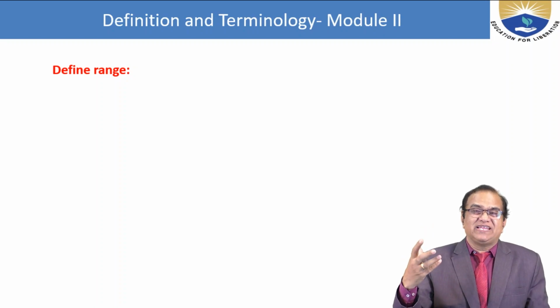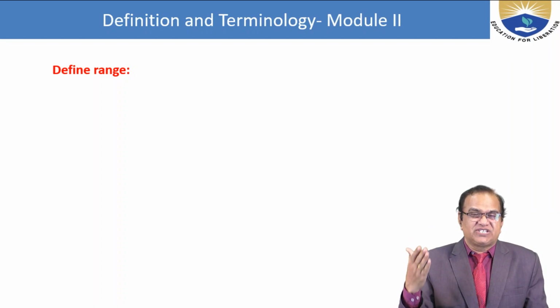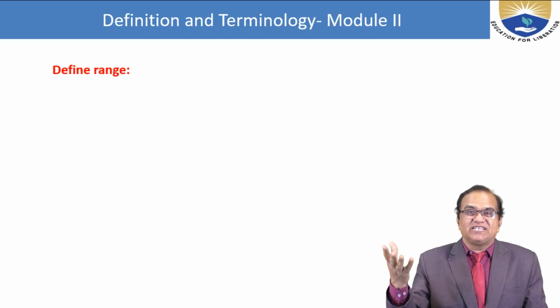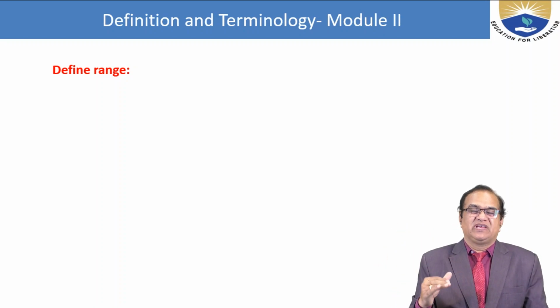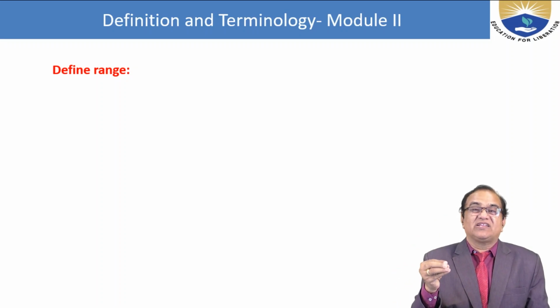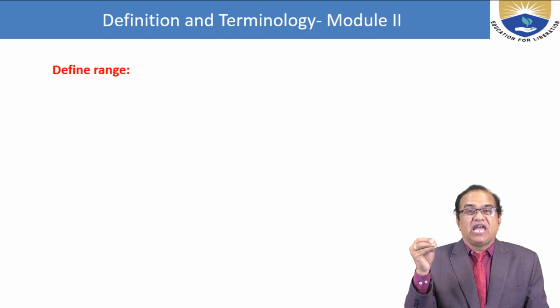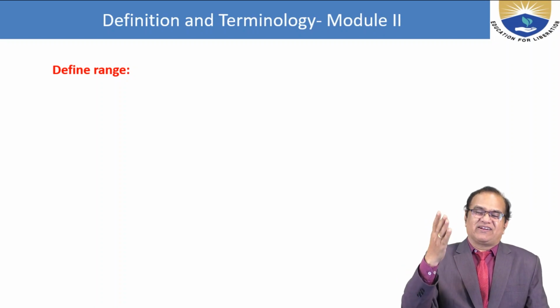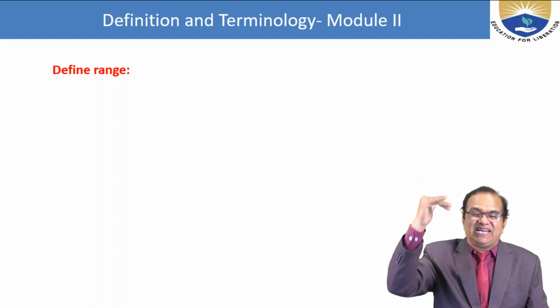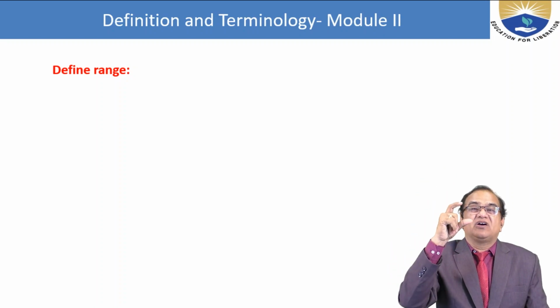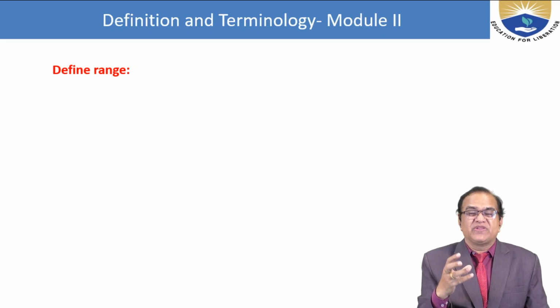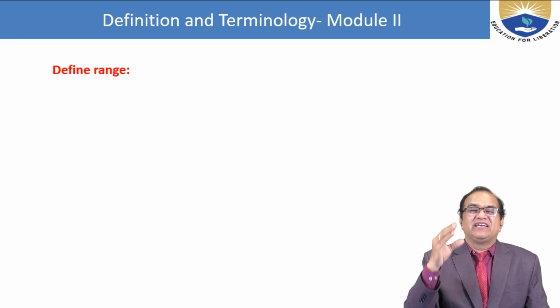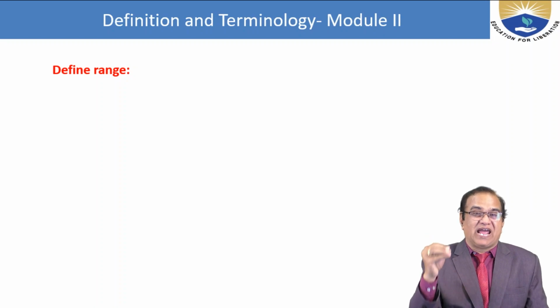If you want to fly the aircraft for a long distance, we should not go at very high speed or very low speed. We have to fly the aircraft at a speed at which drag is the minimum. That is called the minimum drag speed. Every pilot flies at a certain height where the density is very favorable and the speed of the aircraft is such that it generates the minimum drag.